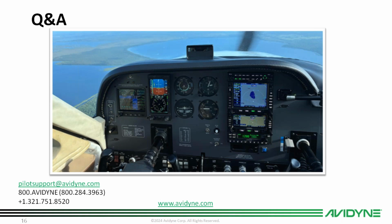We had a question from a gentleman on the GTX 330 ES, whether that requires a wiring change, and it does not, because the wiring change is only for the 345, which has ADS-B in as well as out. I may have it backwards, but the 330 only does ADS-B out, so it doesn't receive traffic and weather, which is what that input that we need a wiring change for from the 345. I don't know if I made that worse or better.